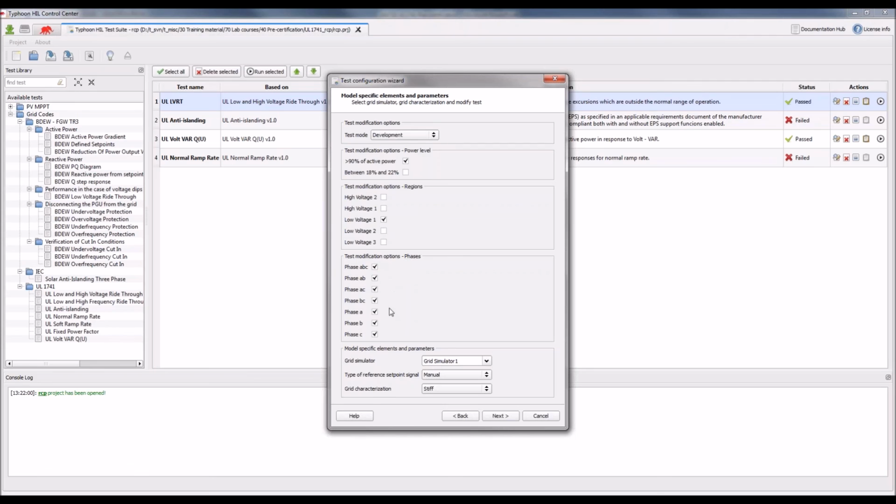On top of that, depending whether it's a 3-phase or single-phase inverter, and we're testing a 3-phase inverter, it requires either symmetric faults, meaning symmetric low voltage ride through, where you're reducing the voltage in all 3 phases symmetrically, or you're looking at all the combinations line to line, where you have dips between A and B, A and C, and phase A, phase B, phase C towards the neutral.